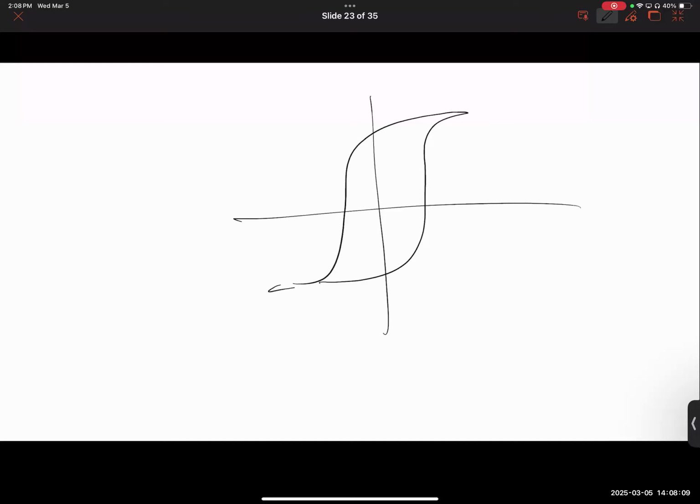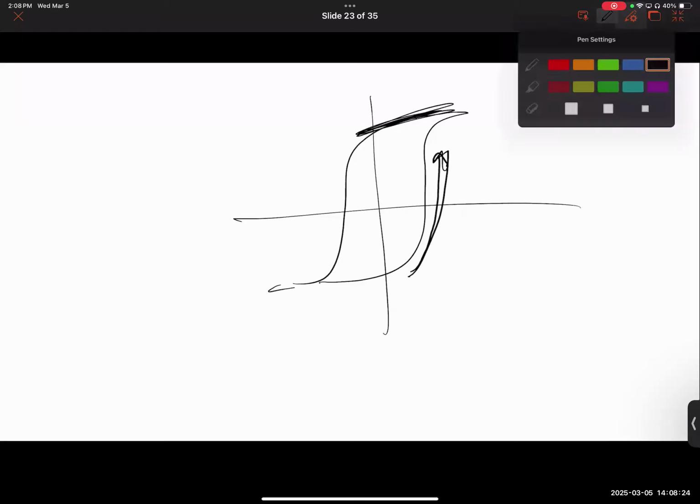So while trying to read, we basically had to go through this route for at least one of the situations. And for the other one, we didn't switch. For one of them, we switched. So that means every time we read, we had to write back. That was the biggest challenge for FE cap based memory. And let me show you why this approach that I just explained, which merges ferroelectric property with the transistor, helps. Let me show you. I'll make a really big plot.